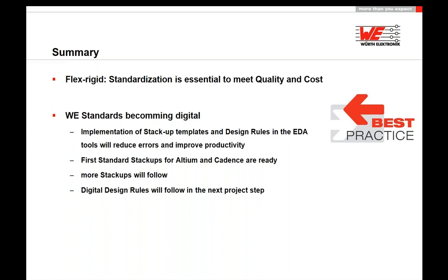And the implementation of these templates, as well for the stack ups, also for the design rules later on in your EDA tool will reduce errors and will improve your productivity. So that's a nice thing we will follow. The first standards we are already providing for Altium and Cadence. They will follow the standards, I think, also for Mentor and for Zuken tools.